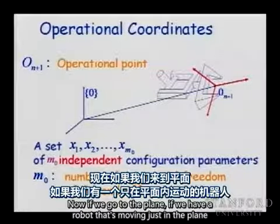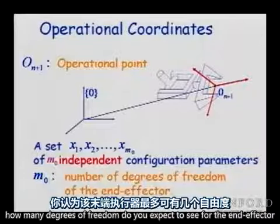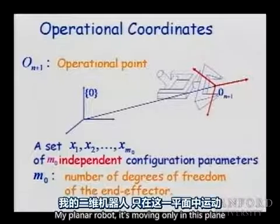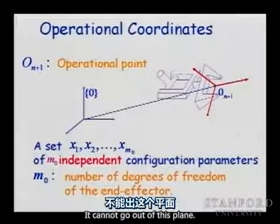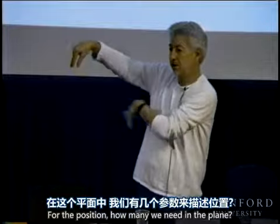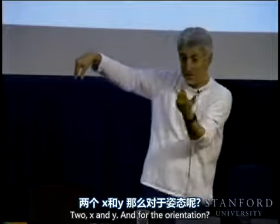Now, if we go to the plane, if we have a robot that is moving just in the plane, how many degrees of freedom do you expect to see for the end effector? My planar robot is moving only in the plane, it cannot go out of this plane. For the position, how many do we need in the plane? 2, x and y.